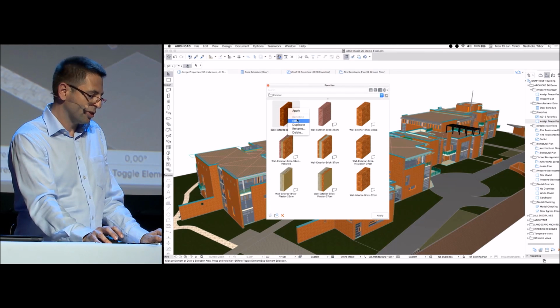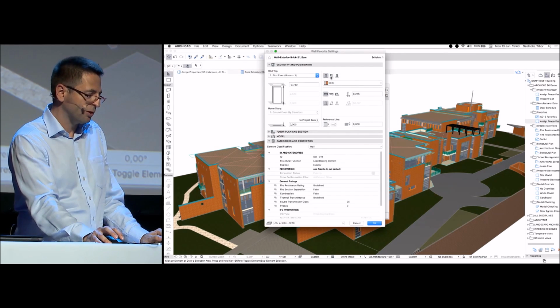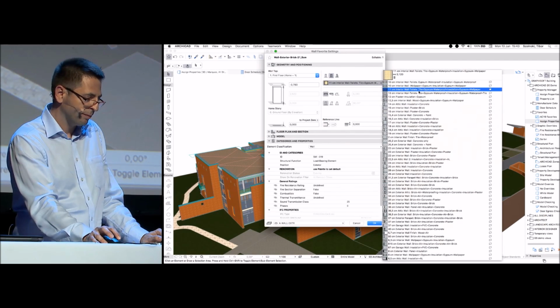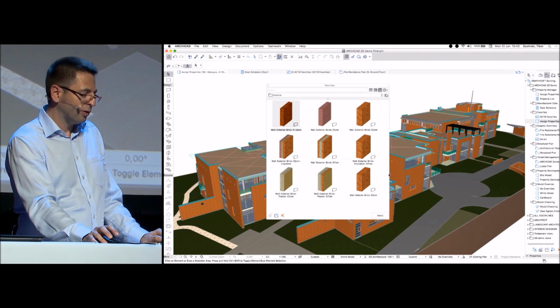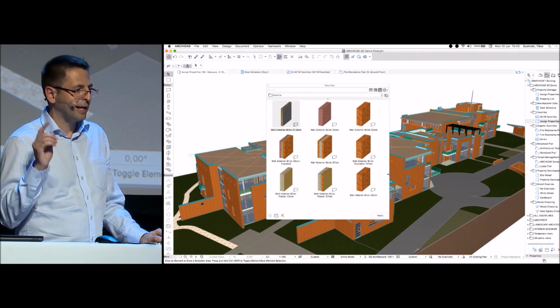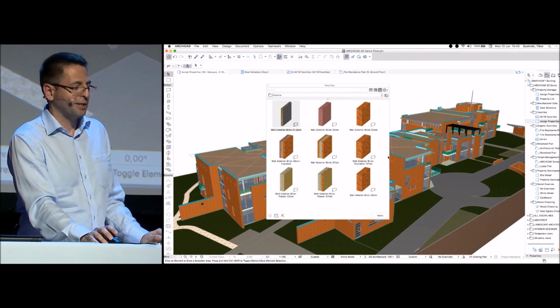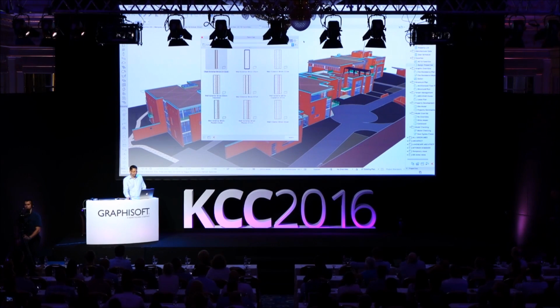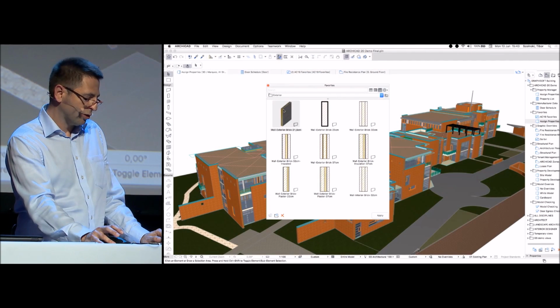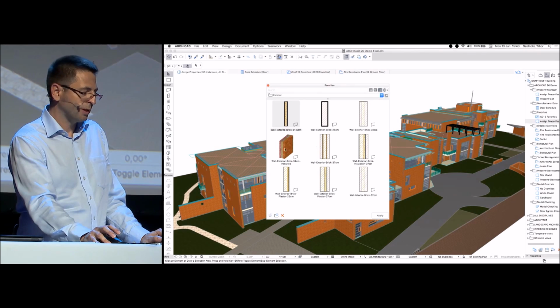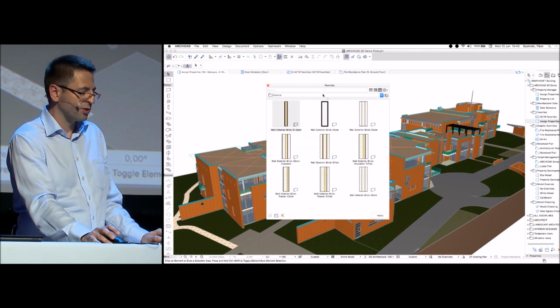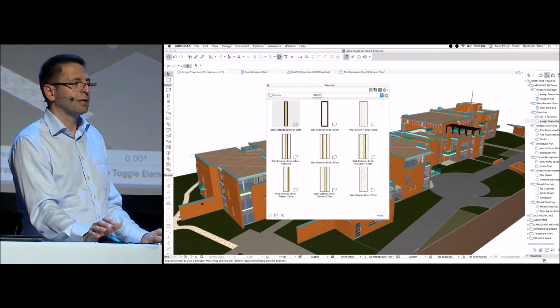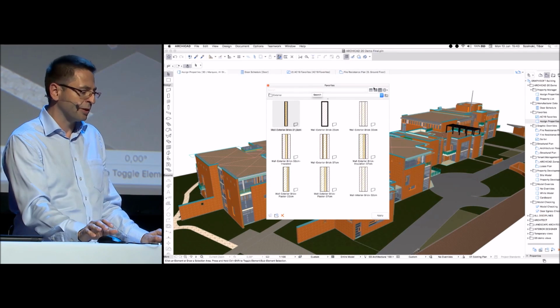All you need to do is just edit one of these favorites. For example, I will choose a different composite structure. And using OpenGL, Archicad automatically updates the previews. That is, again, a real productivity improvement. In certain design scenarios, 2D previews would be more useful. And we can also switch that with a single mouse click. Furthermore, using a control click, you can switch between 3D and 2D views. So I think it's really a convenient way to understand what these favorites are actually used for.